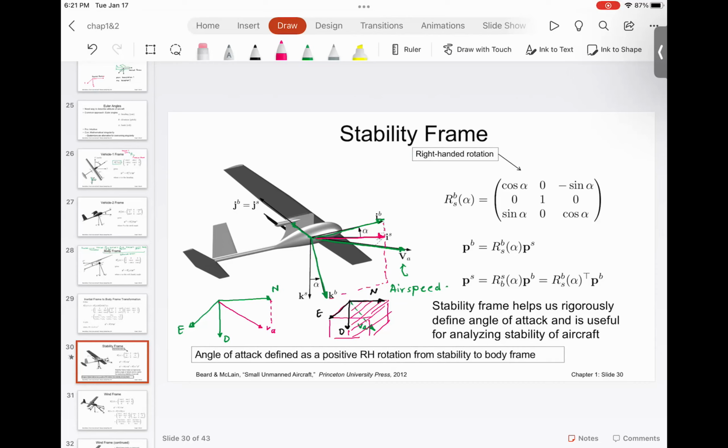Total energy is going to remain constant. Since velocity at the top is greater, the pressure drops. Velocity at the bottom is slower, so the pressure increases. So you get a differential pressure, and that causes the aircraft to lift. This lift is dependent on the angle of attack, which means if you have a flat airfoil, it will not generate tremendous lift. If you start changing the angle, then gradually you will get some lift and some drag. At a critical angle of attack, there is no lift, only drag.